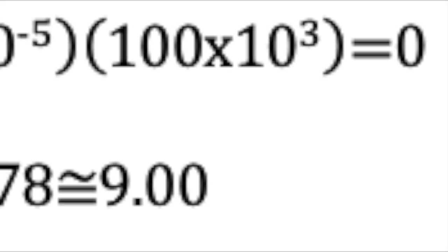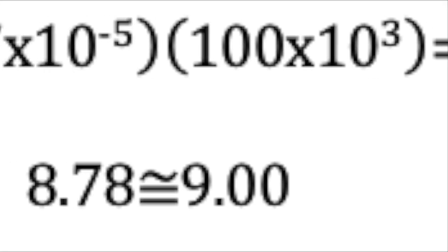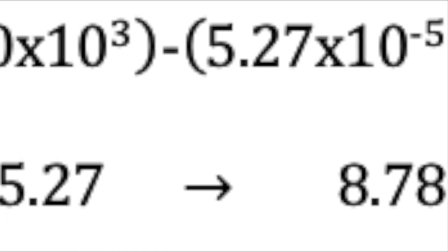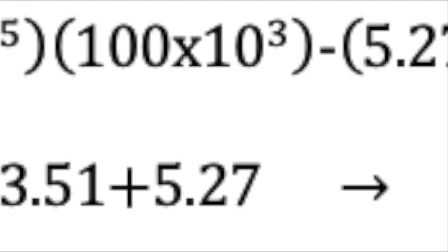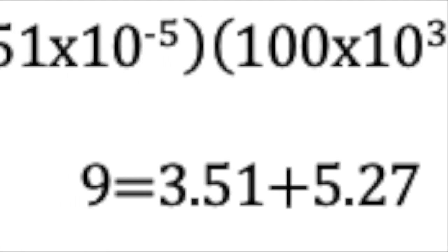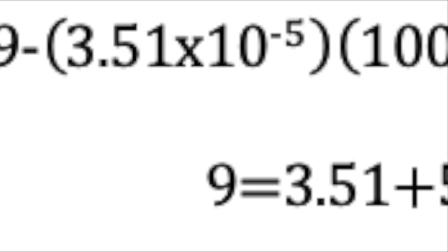For checking the validity of Kirchhoff's loop law, we should apply the rule. And to check whether the measured values satisfy the equation or not, the values are replaced and the equation becomes as follows. As you can see, the total voltage drop in the loop is found as 8.75 plus or minus 0.01 volts, which is not completely equal to 9 volts. This is the result of the loss that happened during the experiment.